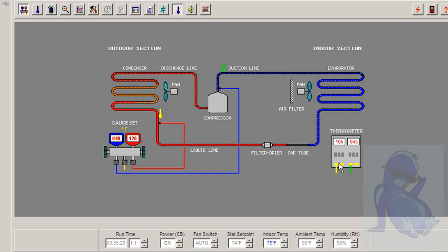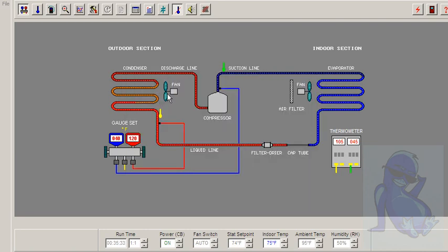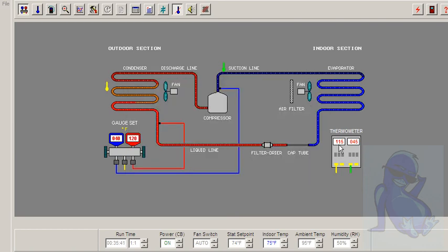Let's see some more temperatures. What temperature do you think is blowing outside your condenser unit? On a 95 degree day, you've got your fan running, blowing across the coil. Let's see what temperature that is. Condenser outlet is 115 degrees, just 5 degrees under the change of state, and about 20 degrees warmer than the outside temperature.